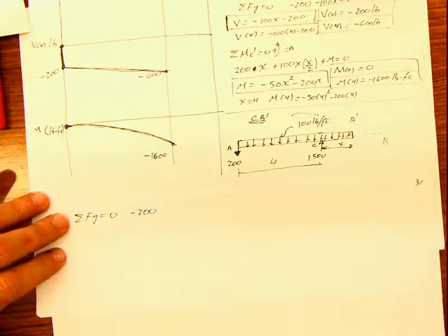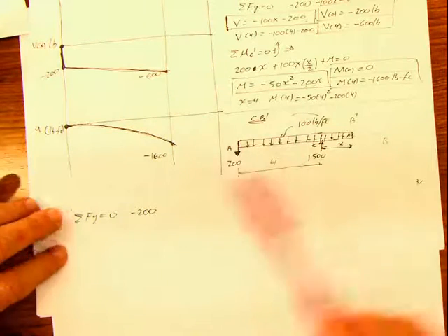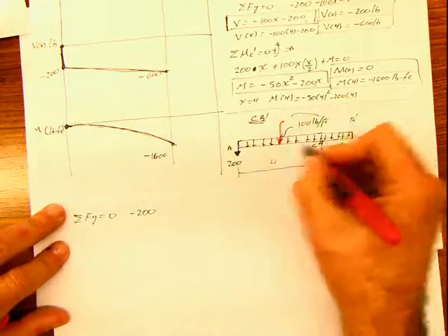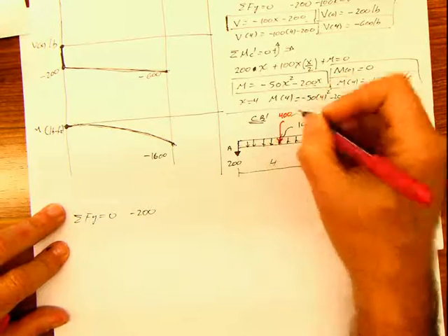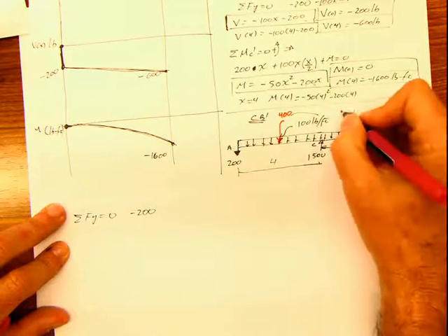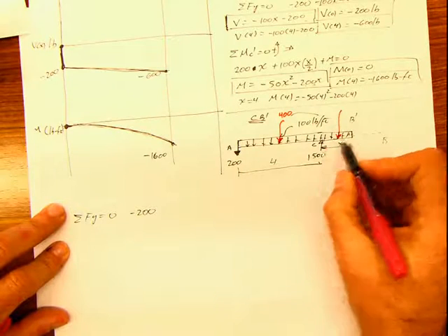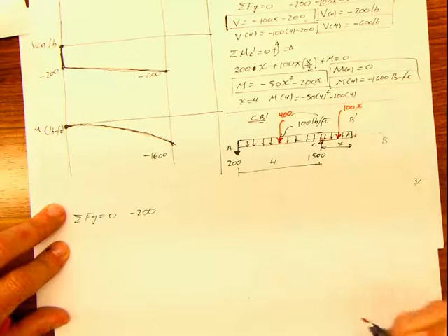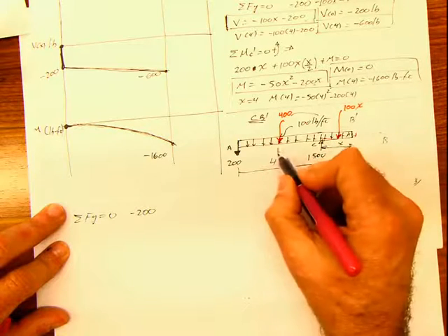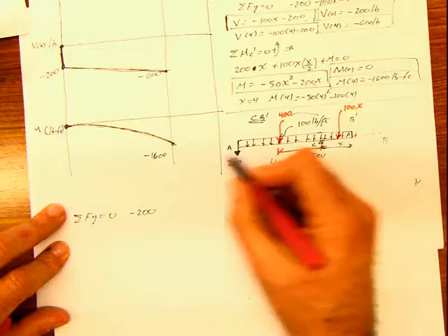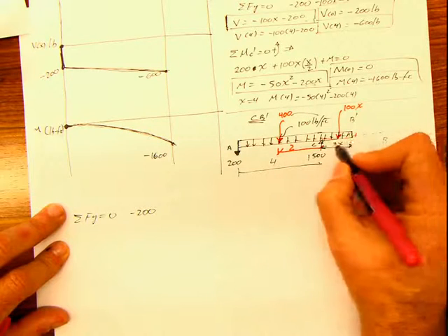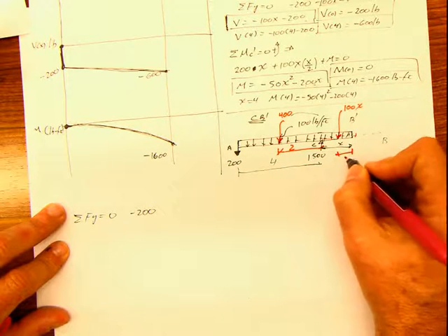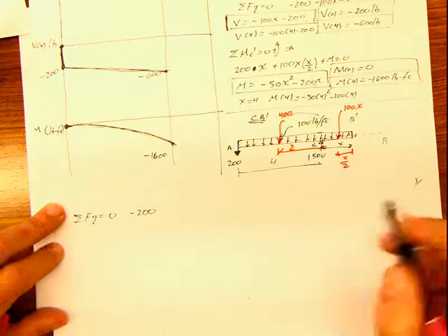Now, you can put this whole thing as one force, but I'm going to divide it in 2 parts. One here, which is 400, meaning 4 times 100, and another one here, which is 100 times x, for the forces. I'm going to mark the distances. This distance here is half of the base, that means this is 2, and the distance from here to here also is going to be half of the distance, which is x divided by 2.